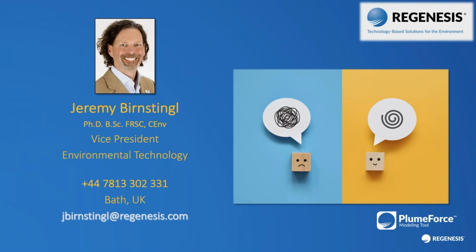The other options that you'd have, which may be easier from the get-go, is to simply tinker with the FOC term in the model, raise it by, say, 200 to 800 times, or indeed you could adjust the individual KOC values that you might have for your contaminants. And again, you'd increase those by 2 to 3 orders of magnitude, typically about 200 to 800 times. And that would give you an idea about how the performance would change on PlumeStop compared to the natural fraction of organic carbon, which you'd probably keep set in there at about 0.001.